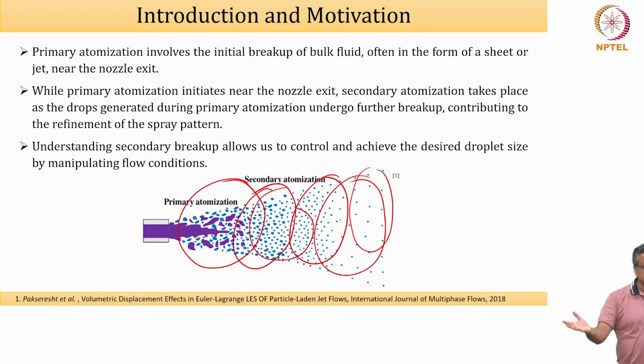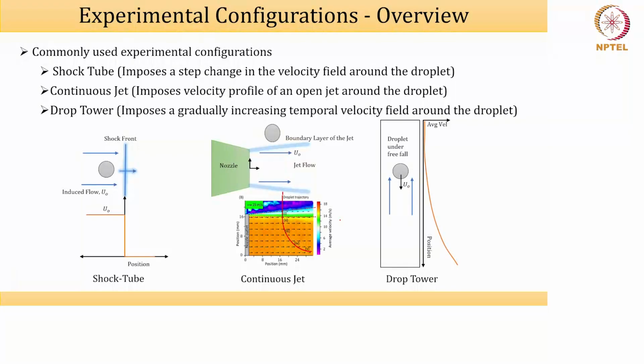And as you know, the flows are notoriously complex, as had been said earlier. When you have swirling flows, shear driven flows and flows like that, they are never uniform. They have strong vorticity gradients, right? And because of that, the dispersion of the droplets is affected. Okay, what we are not talking about today, and maybe we can talk about later, is that the moment this dispersion characteristic changes, the droplet heat and mass transfer also changes. And that actually changes what we call the mixing of the droplet, that is, the mixing of the vapor phase. All right.